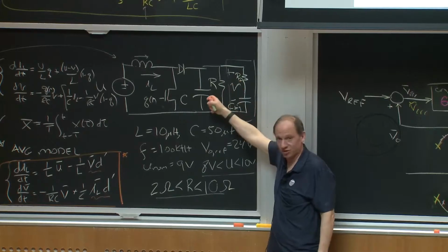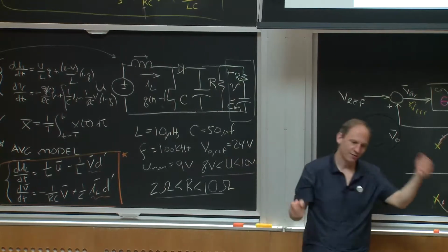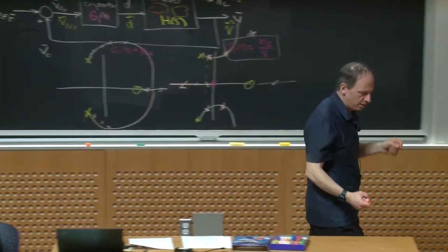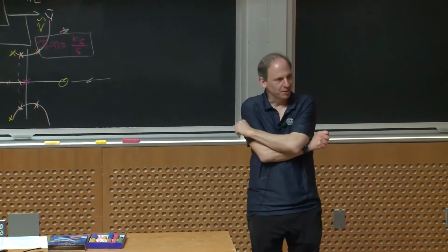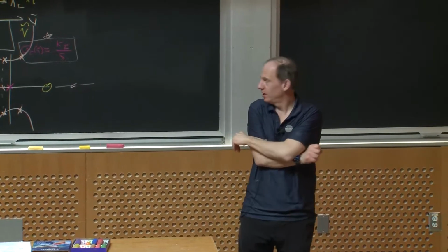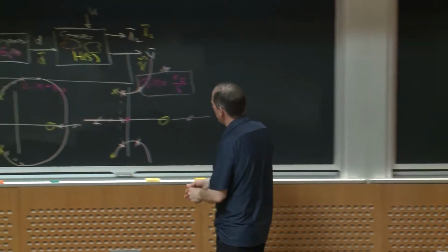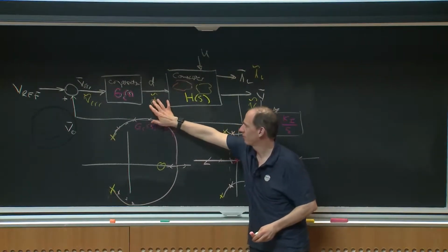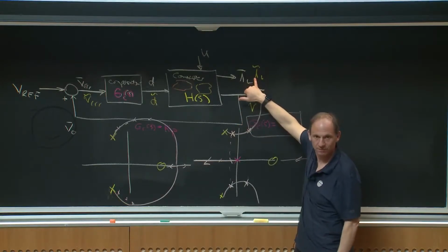So sometimes you have to change things, but you don't tend to like to add hardware if you can do it in control. I'd certainly use a bigger capacitor. The other thing I would probably do in this kind of converter is a different control scheme. You notice that in this control scheme, we reduced everything down to a transfer function from duty ratio to voltage, and I just ignored what the inductor current was doing.